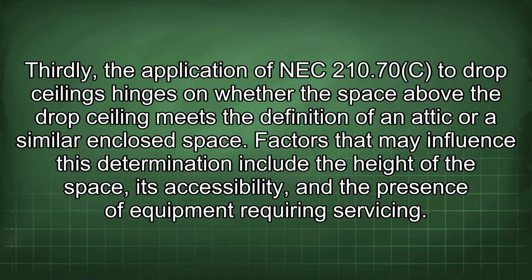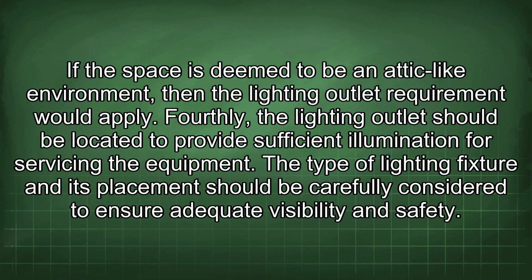Thirdly, the application of NEC 210.70 to drop ceilings hinges on whether the space above the drop ceiling meets the definition of an attic or a similar enclosed space. Factors that may influence this determination include the height of the space, its accessibility, and the presence of equipment requiring servicing. If the space is deemed to be an attic-like environment, then the lighting outlet requirement would apply.